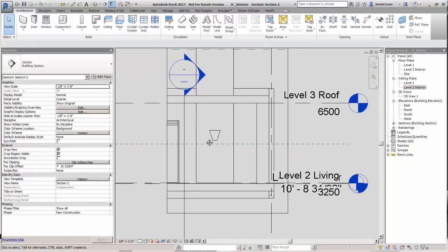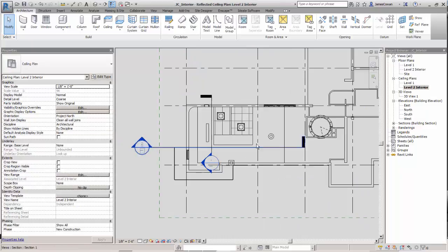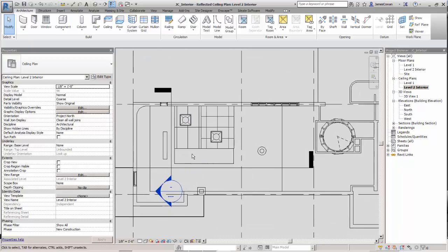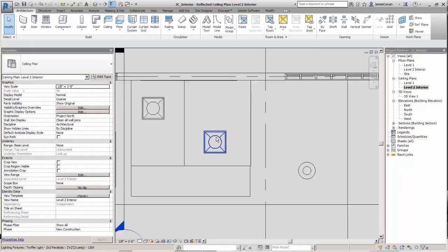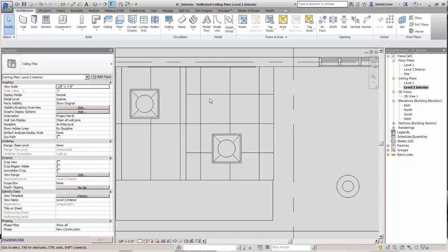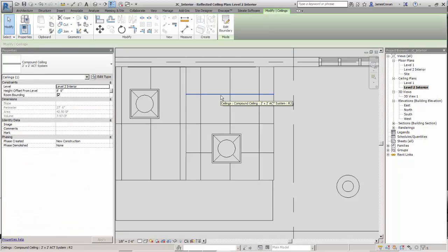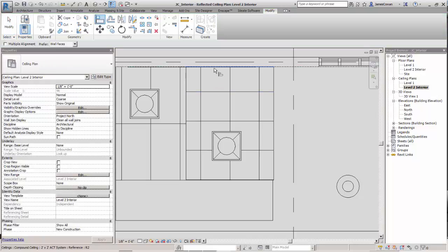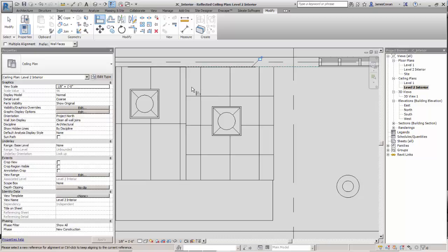However, this is really not about lighting so much as it is about the ceilings. We're going to come back to the lighting later on. So if I go back to my ceiling plan, I've got these 4 types of ceiling. I next wanted to show that the objects that are on the ceiling, if I just select one of those lines, you see they're actually attached wherever you drop them on there. And you can use the align command, AL, to manage your pattern. So in other words, align to inside face of this ceiling, that line.